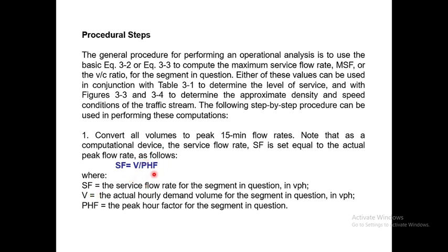Definitely, PHF would be given information in the final exam. Okay, we will give you the peak hour factor, because you can also calculate the peak hour factor, but this is given information. And also the V, the actual hourly demand value. So when you divide V over PHF, you can calculate the service flow.